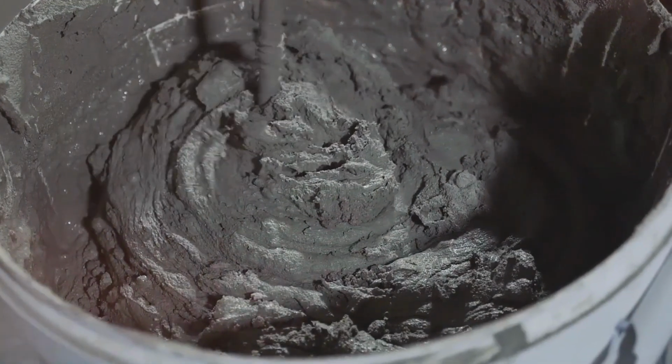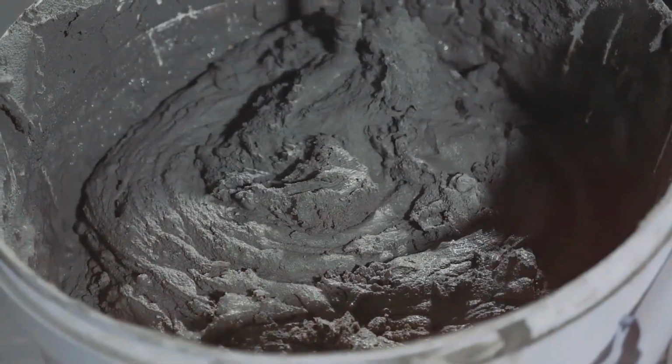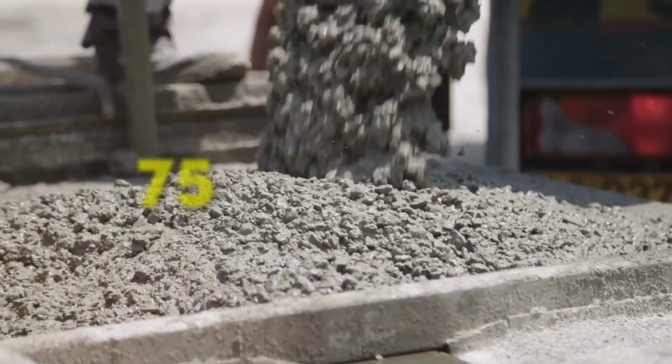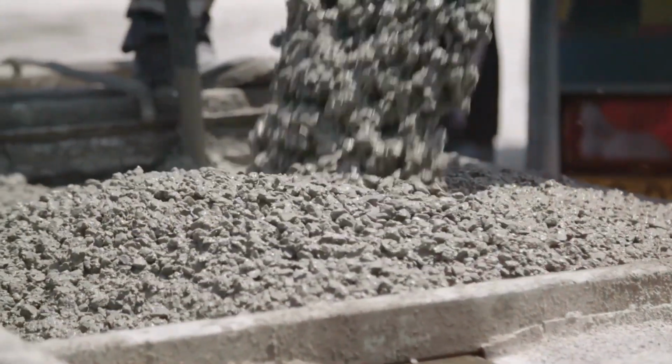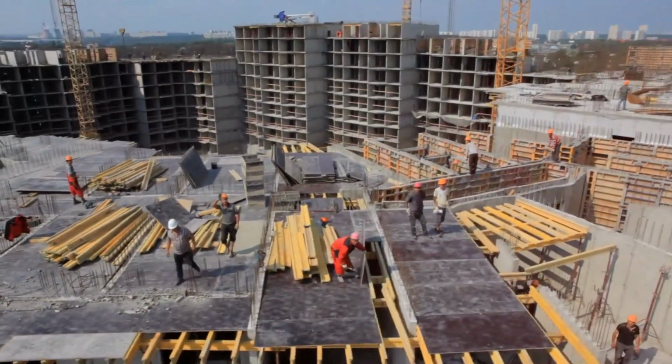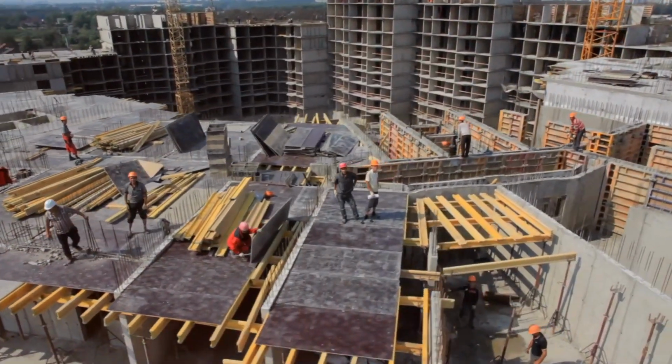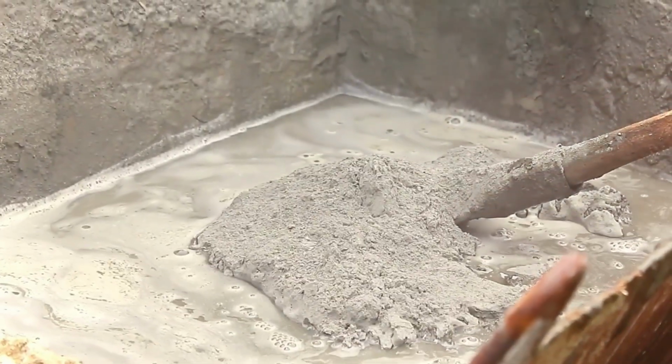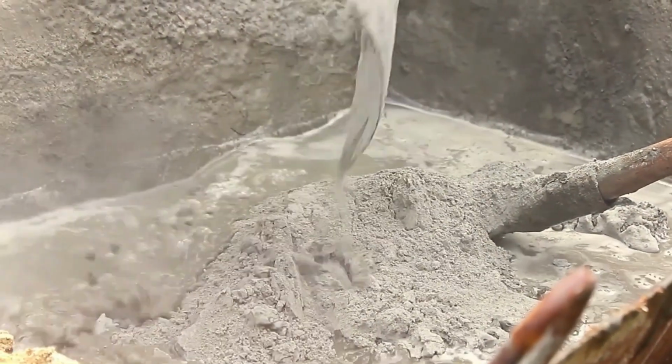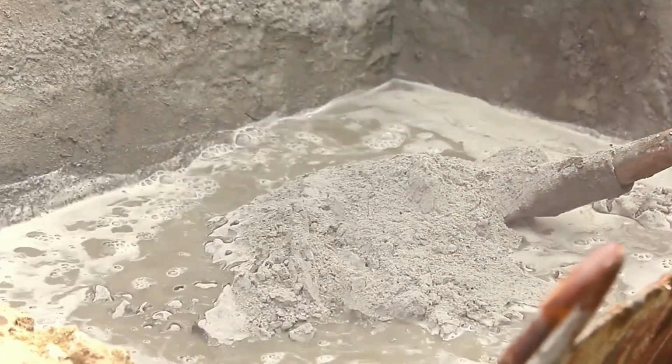Now that the cement is ready, we shift our focus to obtaining the aggregate, which can make up to 75% of the concrete volume. The aggregate, composed of gravel and sand, undergoes careful selection and mixing. A well-graded aggregate, with a balanced mix of coarse and fine particles, reduces the need for cement and contributes to the cost efficiency of the entire process.